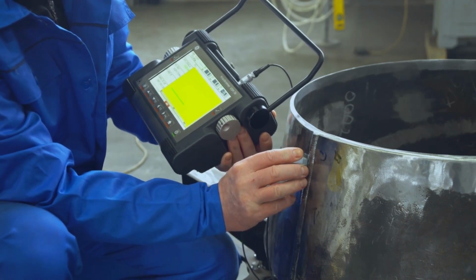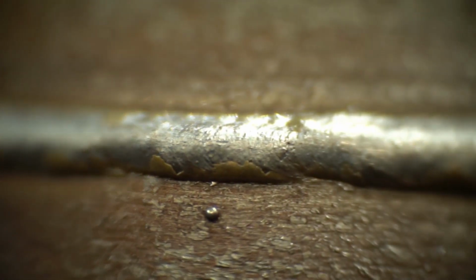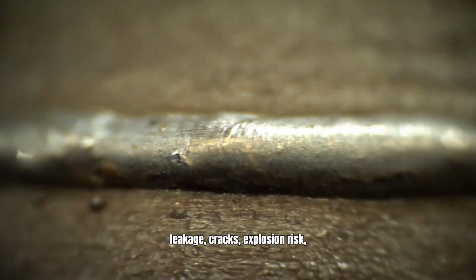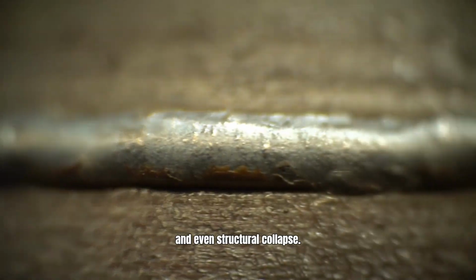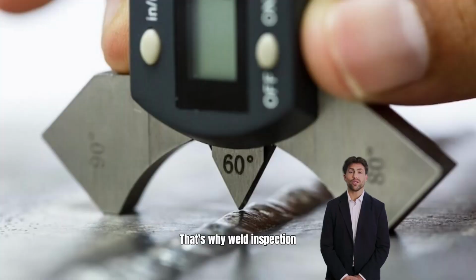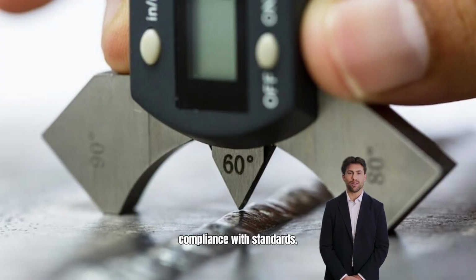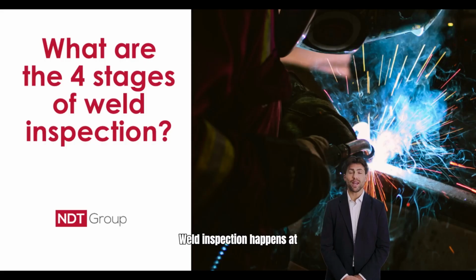Let's begin. Welding joins metals permanently, but a bad weld can cause equipment failure, leakage, cracks, explosion risk, and even structural collapse. That's why weld inspection is done to ensure strength, safety, durability, and compliance with standards. Weld inspection happens at 3 stages: before welding, during welding, and after welding.